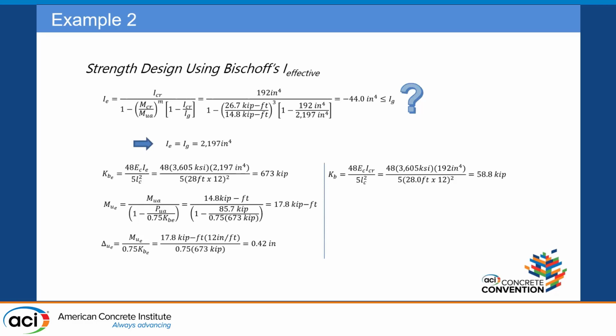If we go back and did it the correct way and we use the cracking moment, here's our, well, in this case, we got a negative moment now. So now here's our moment, and now we've got a negative moment of minus 15.7 on this panel. Okay. So there ought to be some red flags at this point if you're doing design this way. If you're using software and it's doing something like this, you're not going to see it because it's in the black box.